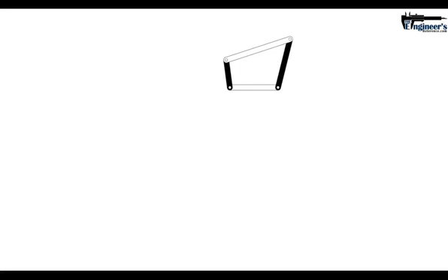Now again, let's look at this a little bit more. If we have the still picture and then we have it animated, hopefully you can see how this looks more like a windshield wiper motion, where we have the shortest link next to a fixed link, and the longest link, and you're getting this complete rotation, and then you see this rocking motion on this one. But let's go through a few things.